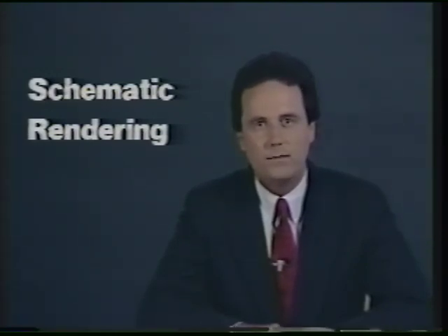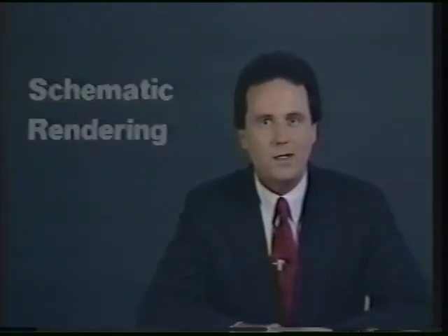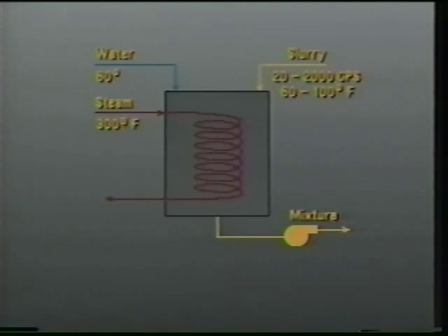At this point, the sketch should only include the process itself, without any indication of control valves, sensors, analyzers, controllers, or other instrumentation. In this example, the process sketch shows that water and a slurry are mixed in a vessel. Heat is then added to this mixture through the mechanism of a steam heat exchanger. After the mixture is heated to some specific temperature, it is pumped out of the vessel.